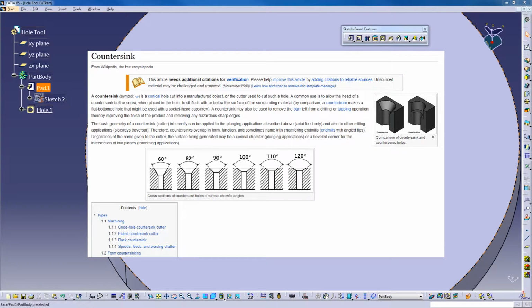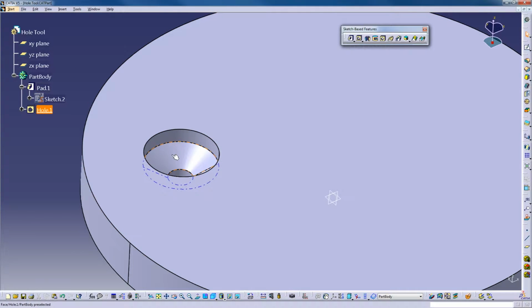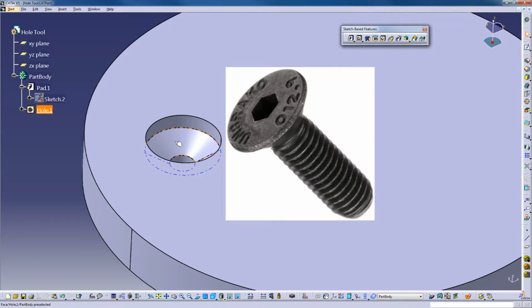Now there's another thing that I just want to mention here too, is that I will go to the store and I'll buy a countersunk screw, but if you look at this picture here, you'll see that the angle on the edges of the countersunk, the top edges here, they don't come to an infinite perfect sharp point. They always tend to be a little bit rounded. And so if I just went by the angle and assumed kind of like a digital model, perfect, sharp, flat fastener here, I might end up with a problem.